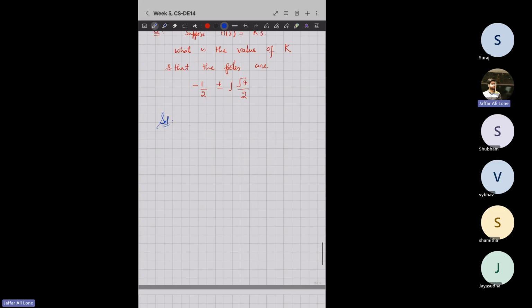I'll just give you the characteristic equation based on the poles. You just have to find the characteristic equation in two ways. Then just compare and you'll get the answer. You solve it, you'll get s square plus (k minus 3) into s plus 2. This should be your characteristic equation. Oh, sorry.